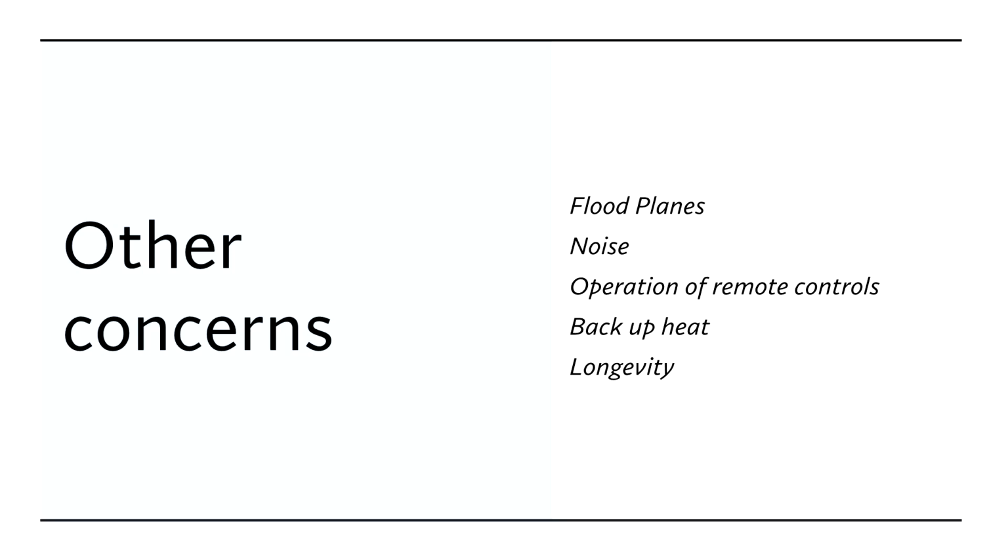Set the fan speed and set your temperature, and then forget it and put the remote someplace where you can get to it if you need it, but don't go constantly changing it up and down. They don't work like your wall thermostat for your hydronic system or your furnace, where if you're cold, you crank it up. These actually work on a longer, consistent cycle.